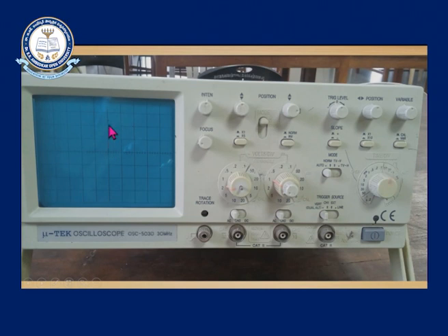So 1, 2, 3, etc. At the same time here it is also 1, 2, 3. So where these lines coincide, that is the units. So how many units, that value multiplied by time for voltage; don't take the time values there, only the observation value. The x axis value multiplies time, and the y axis value multiplies voltage. That is the concept of this value. Okay, you observe the waveform.